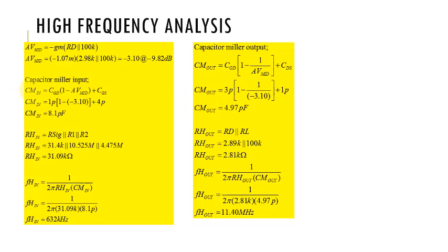So at the capacitor Miller in, we have CGD. When we apply this, firstly we need to determine the AV, which we obtained from our first chapter. So this one is the 3.10, and we put exactly 3.10 here.